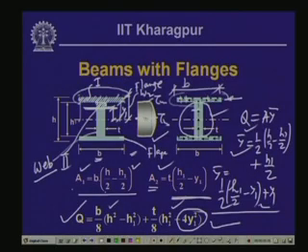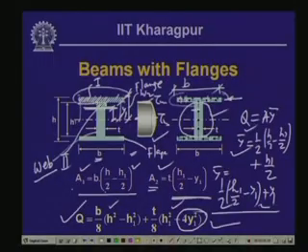So, we will get the maximum shear stress over here, and this will give us the value of the minimum shearing stress. Now, at this particular section you can appreciate that, since we have said the shearing stress is 0 on the surface of the section, if you look into the bottom part of this beam at this section, here the shearing stress is 0 and at this particular section shearing stress is minimum. Hence, at this particular cross section there is a complex distribution of the shearing stress, and as a result we cannot apply the shear formula for evaluating the shearing stress in the plane zone.